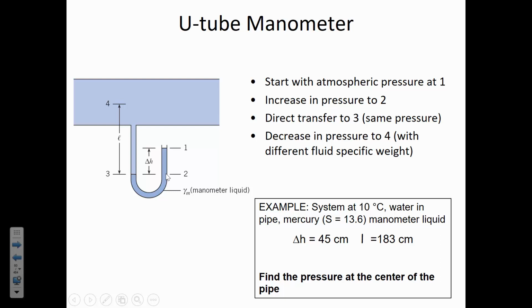Okay, so P4 is going to be 60,037 pascals minus 1.83 meters of water times 9810 newtons per meter cubed. And this change in pressure is going to be a decrease of 17,952.3 pascals.